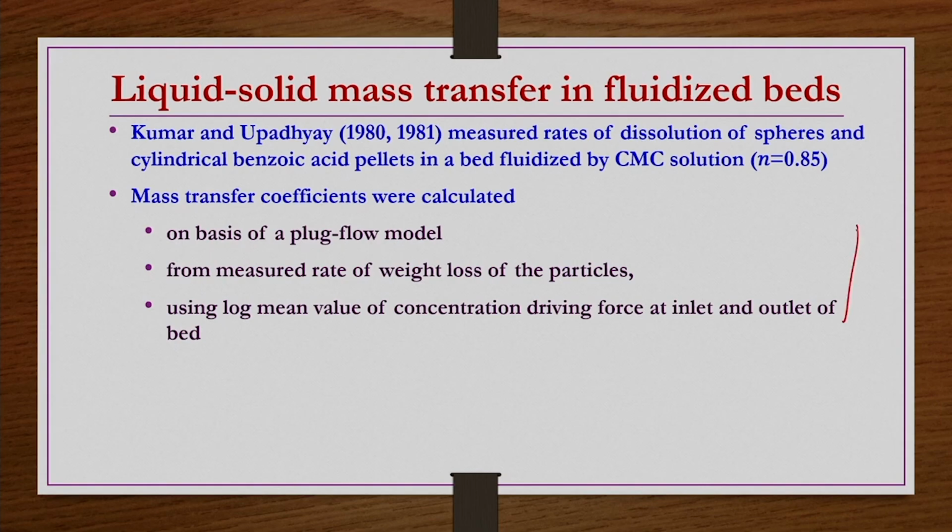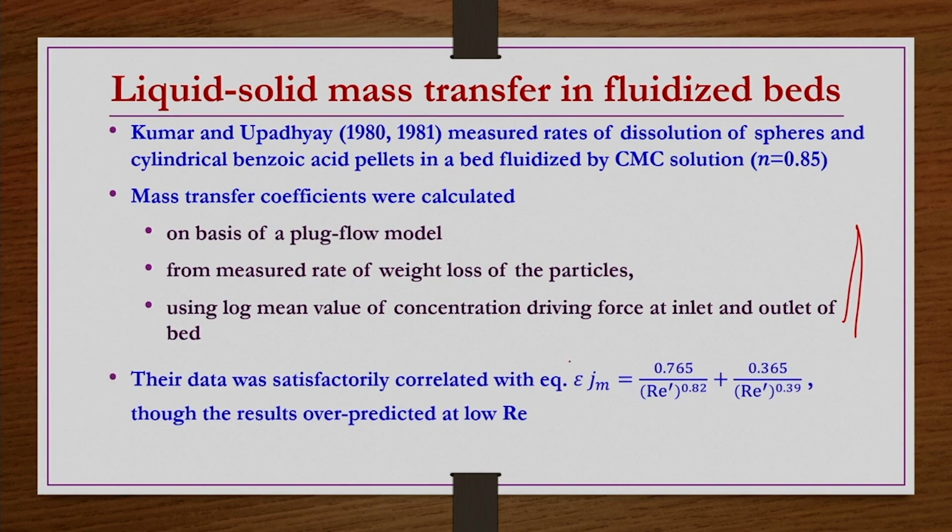Under such conditions they measured the mass transfer coefficients, and they found that their packed bed correlation, developed for mass transfer in packed bed conditions, may be used without any problem, but however this over predicts at low Re.